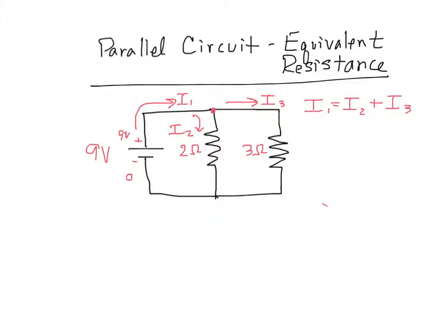So when you think of it that way, then the wire, basically, you're not going to lose any voltage in the wire. We're going to pretend it's an ideal wire with no friction. If you want to think of resistance as friction in a system, we can assume that you still have your same 9 volts at this point right here, and you've got 0 volts down here at the bottom because this is at the same point in the branch as the negative terminal of the battery. There's no resistors between those two dots, so there's no place to lose voltage across that wire.